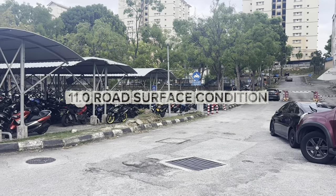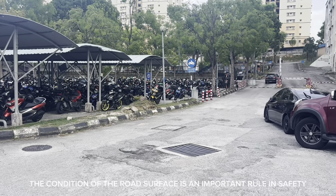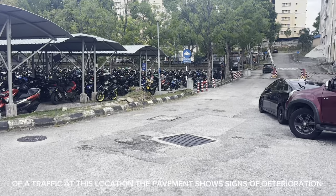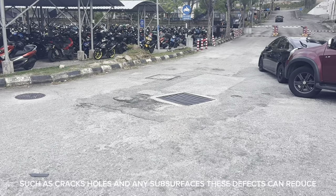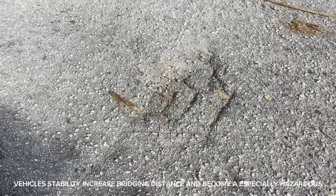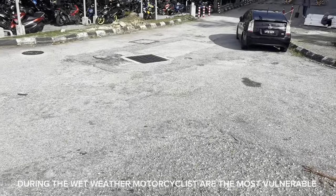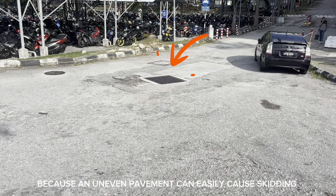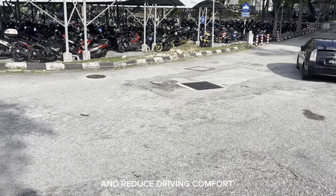Road surface condition. The condition of the road surface plays an important role in the safety of traffic. At this location, the pavement shows signs of deterioration such as cracks, potholes, or uneven surfaces. These defects can reduce vehicle stability, increase braking distance, and become especially hazardous during wet weather. Motorcyclists are the most vulnerable because an uneven pavement can easily cause skidding or loss of control. Poor road conditions may also damage vehicles and reduce driving comfort.